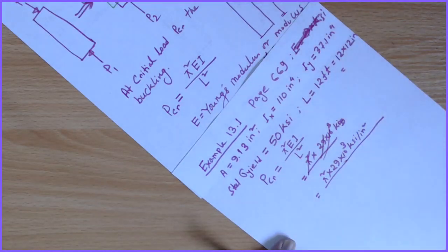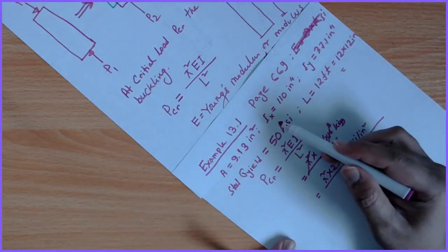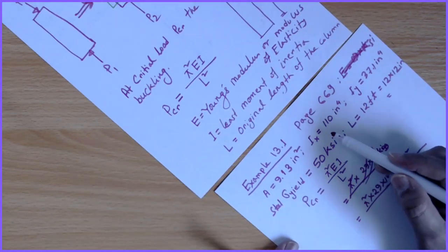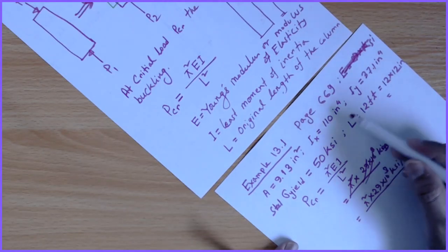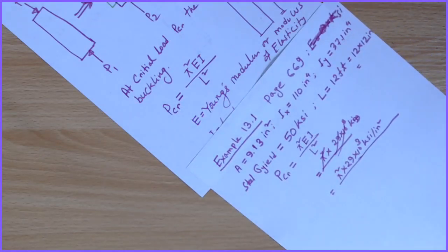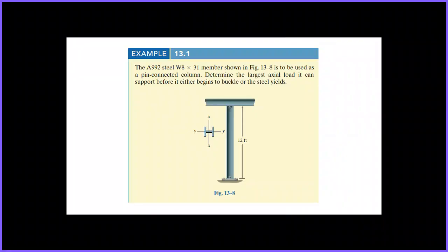The next question is which moment of inertia to take, Ix or Iy. You need to look at the orientation of the section. The orientation is such that the YY axis is horizontal, so we take the horizontal section.